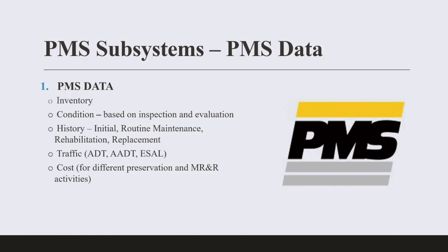The dependent variable, which you use your prediction against, which is the condition of your bridges from 0 to 9, as we said, that's how we do it in the US, or PCI, or some states, they call it PCR, pavement condition rating. That's the y coordinate.